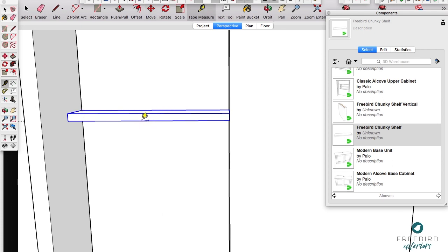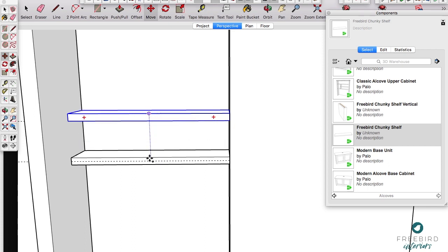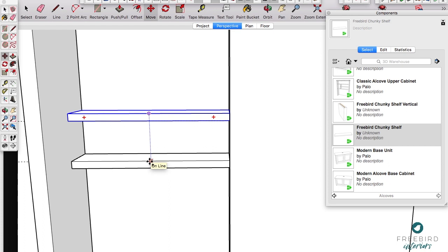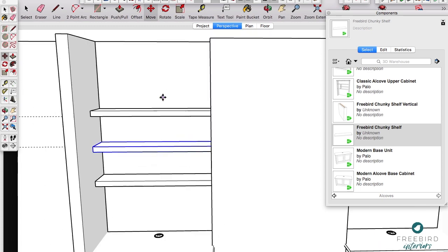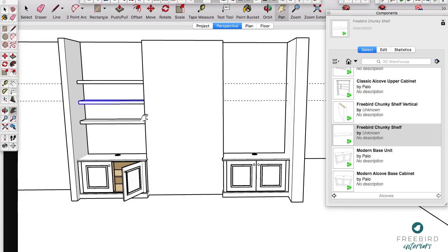Now what I'd typically do is space these apart, generally 300mm, so I can copy that. That's Alt click, might be different on Windows, with the move tool, that copies it. Do that once, and then you do x2 down the bottom right there, and that repeats the operation twice. This would be a fairly typical setup.